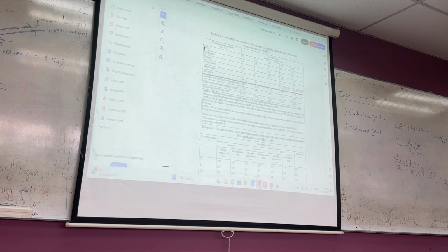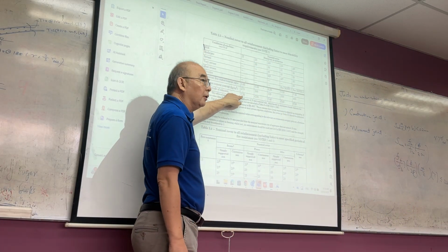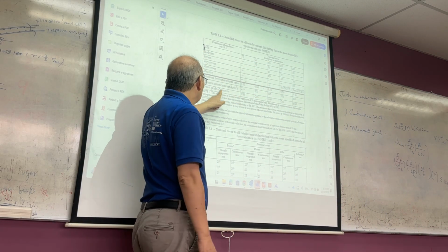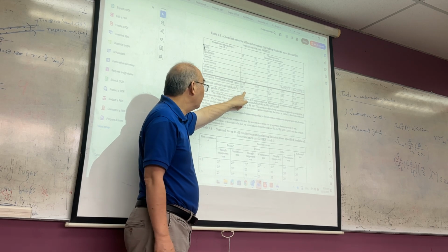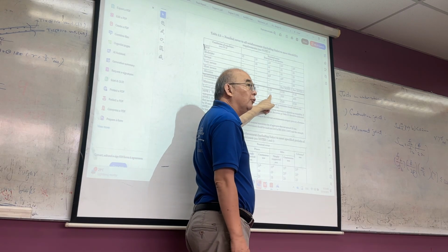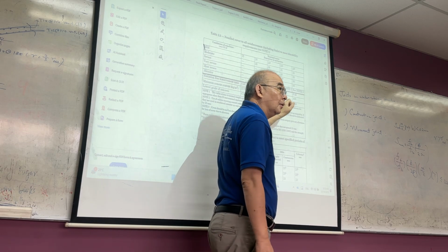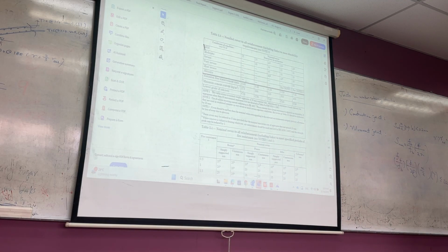Okay. If you look at this code, table 3.3: lowest grade of concrete C30, minimum cement content 275 kg per meter cube, C35 300, C40 325. This is in the code, BS 8110. So this one is a cylindrical one, right?